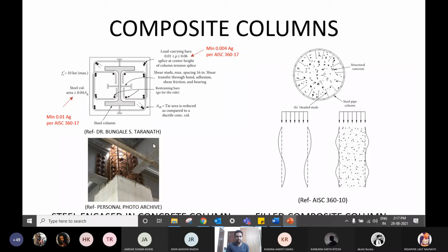Like you can see, a beam can come and join. There's some plate inside which is welded to the steel section inside, and you have bolt connection where this particular beam can come and get itself joined to the column, and you can cast the concrete surrounding it. So in terms of construction, things could be faster here, and the connections are kind of simple.